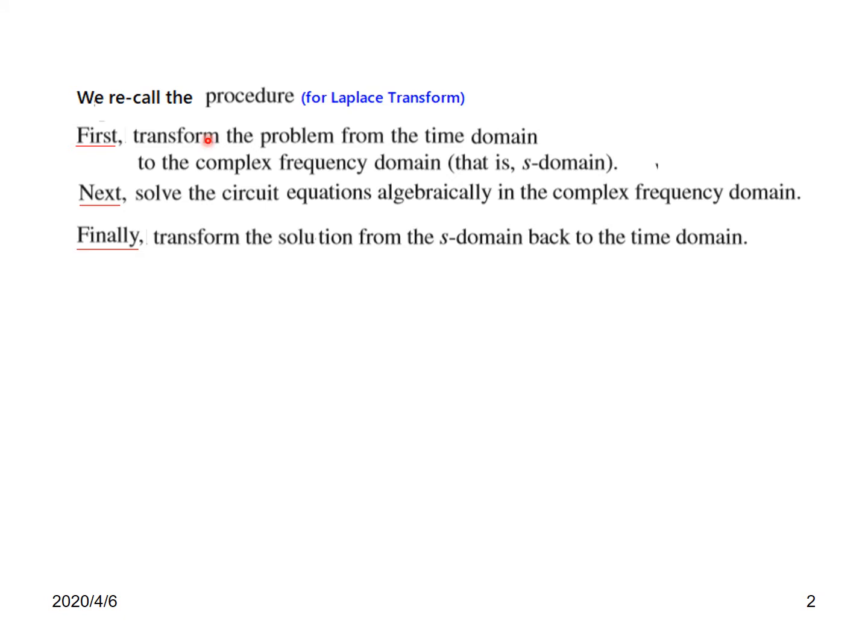First we transform the problem from time domain to complex domain or S domain while doing Laplace transform. And then we solve the circuit in complex frequency domain. And then we revert back to time domain. Now this process of reverting back into time domain is the inverse Laplace transform that we'll talk about here.